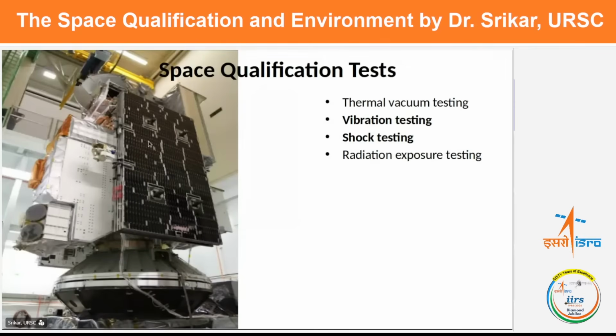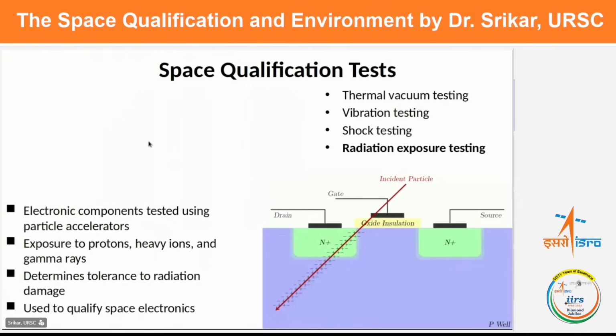And then, as I mentioned, there is huge radiation, all types of radiation, that I don't want to repeat. But whenever high energy particle radiation happens to pass through our sensitive electronic systems, it does deposit a lot of charge into their active medium. And due to that, there can be what we call radiation dose damage to the detector systems, or semiconductor systems, because most of our electronics is based on semiconductors, and they are very susceptible to incoming particle radiation.